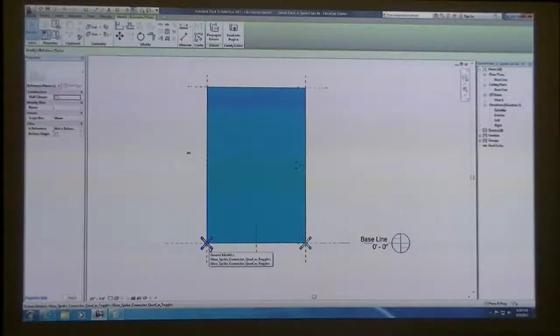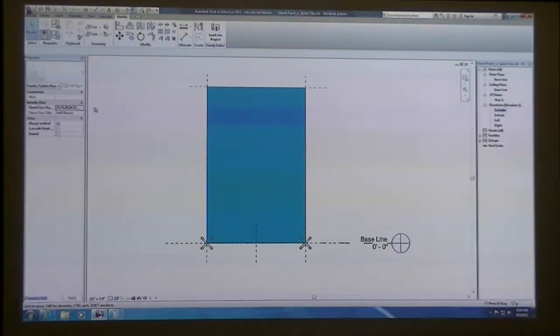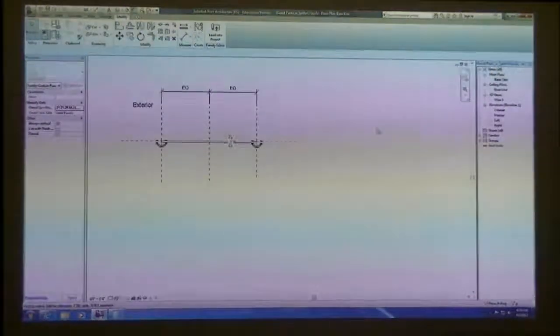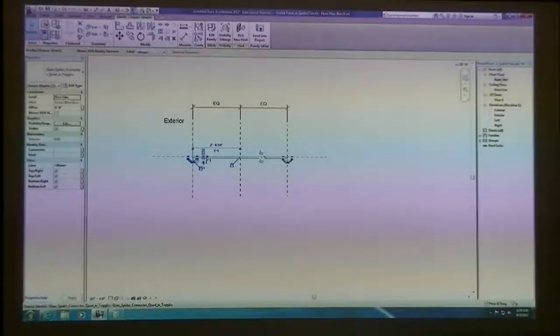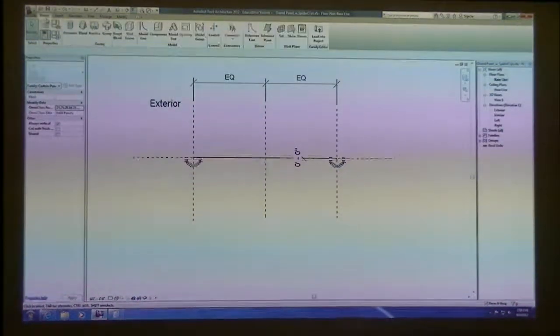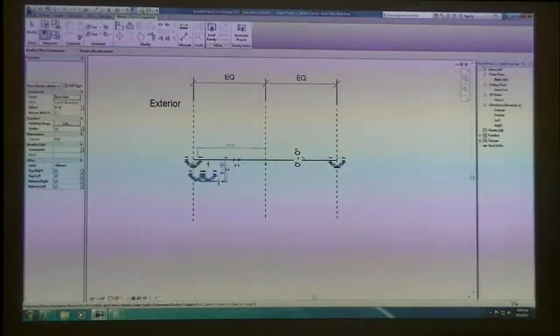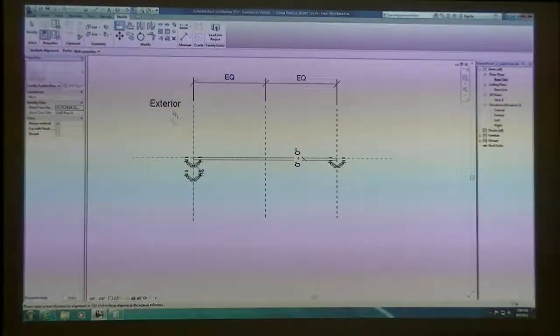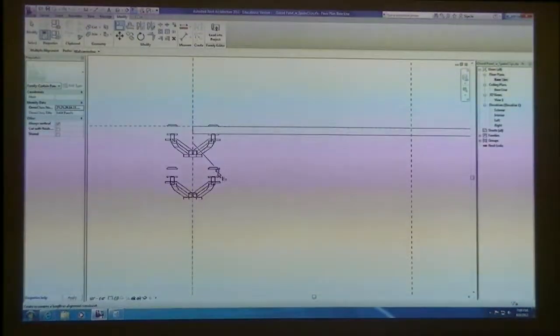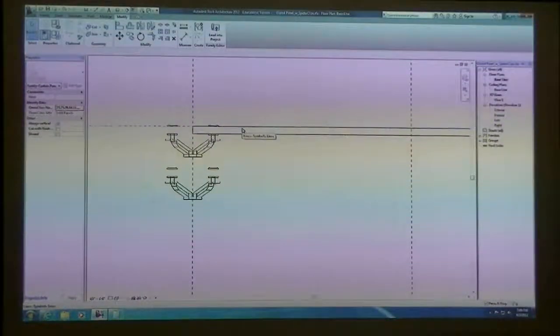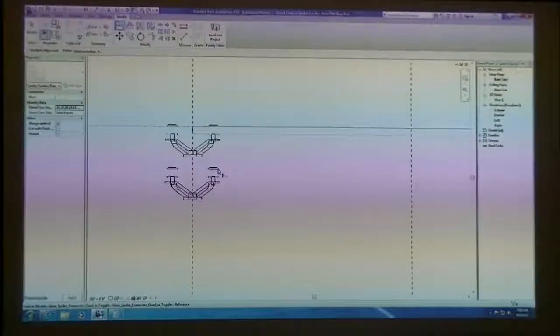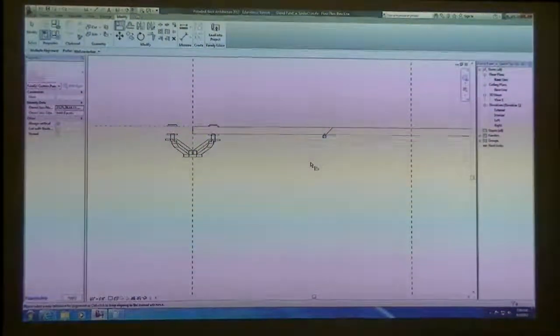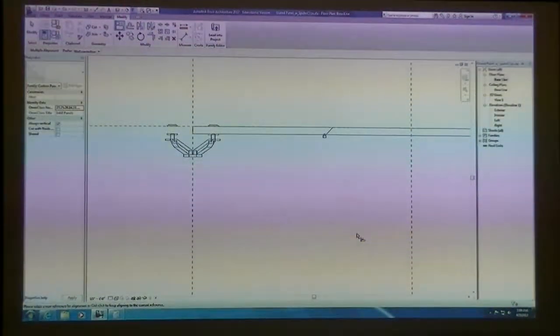So what I need to figure out is, if this is my template that I'm given, how do I get my spider clip up to this particular location, and also get it to move with the panel. If I go back into the floor plan, I'm going to do a home component and place another spider clip, just one more. Again, I'm going to align this to the reference plane on the left and lock it. I can do the same thing where I align it. So basically I'm doubling up exactly where the other spider clip has been placed. And you get an error that says you have identical instances in the same place, and that's okay for now.